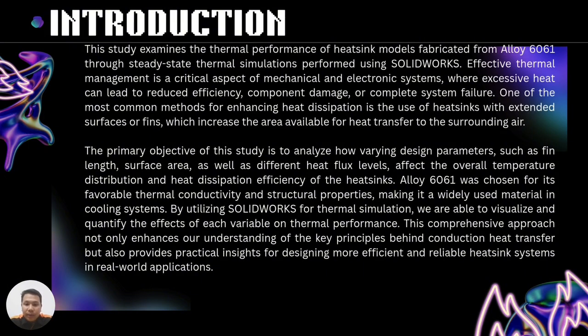Alloy 6061 was chosen for its favorable thermal conductivity and structural properties, making it a widely used material in cooling systems. By utilizing SolidWorks for thermal simulation, we were able to visualize and quantify the effect of each variable on thermal performance. This comprehensive approach not only enhances our understanding of the key principles behind conduction heat transfer, but also provides practical insight for designing more efficient and reliable heat sink systems in real-world applications.